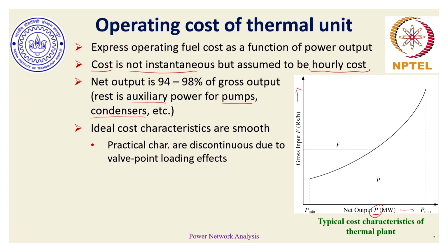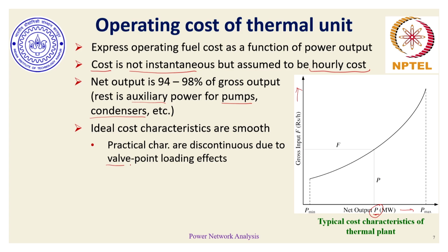As temperature changes from a few hundreds of degrees to thousands of degrees, the corresponding power output change with respect to boiler input or fuel input, which is the coal or the gas, has a nonlinear relationship, and that's what we call valve point effects.